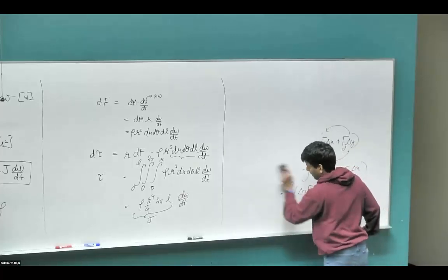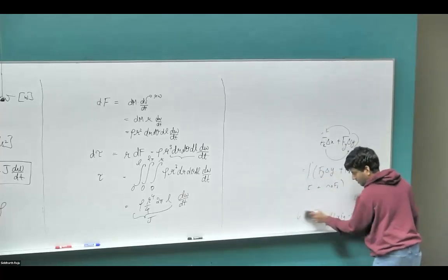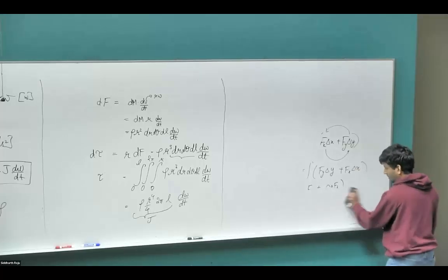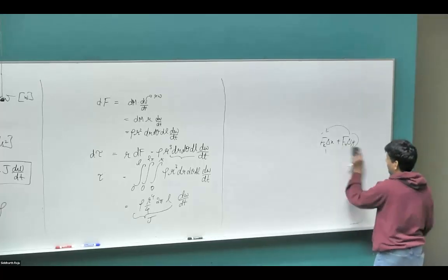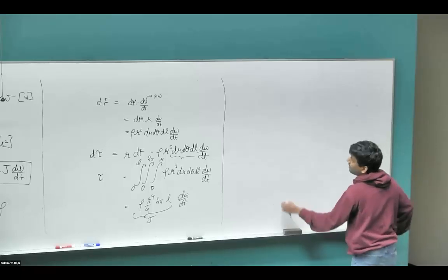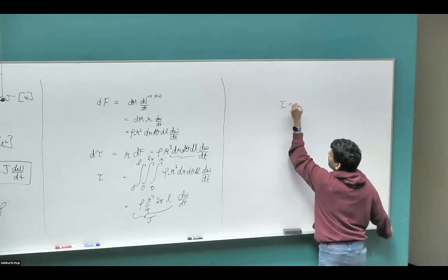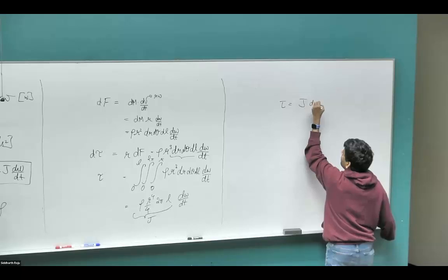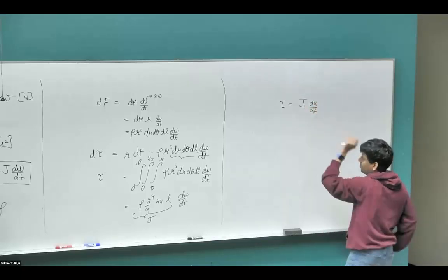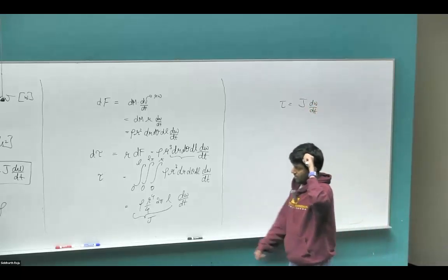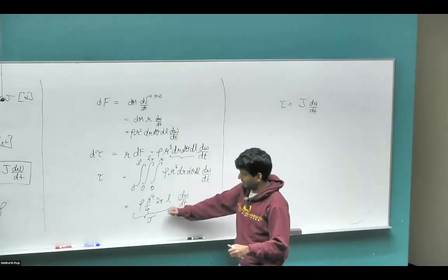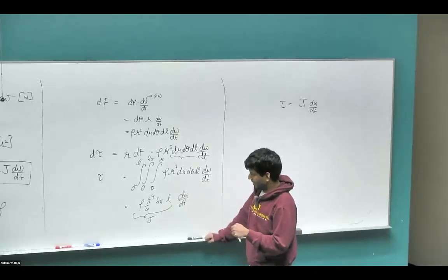for a spinning steel, or any material that is not getting deformed, the torque is going to be equal to J times d omega by dt. If you assume it to be a pure cylinder, this is the expression for inertia. If you assume some other shape, the inertia of course changes.